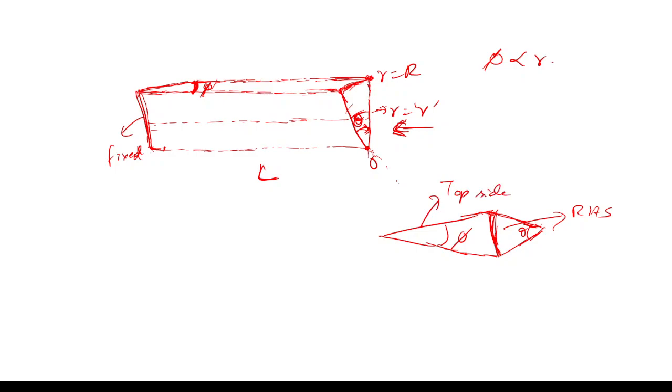Yes, sir. And this shear angle actually reduces when I'm moving towards the center. That's the point I want to make. This shear angle actually reduces. Here I'm marking it as phi dash, and it will be 0 at the centroid. Okay, understood now?